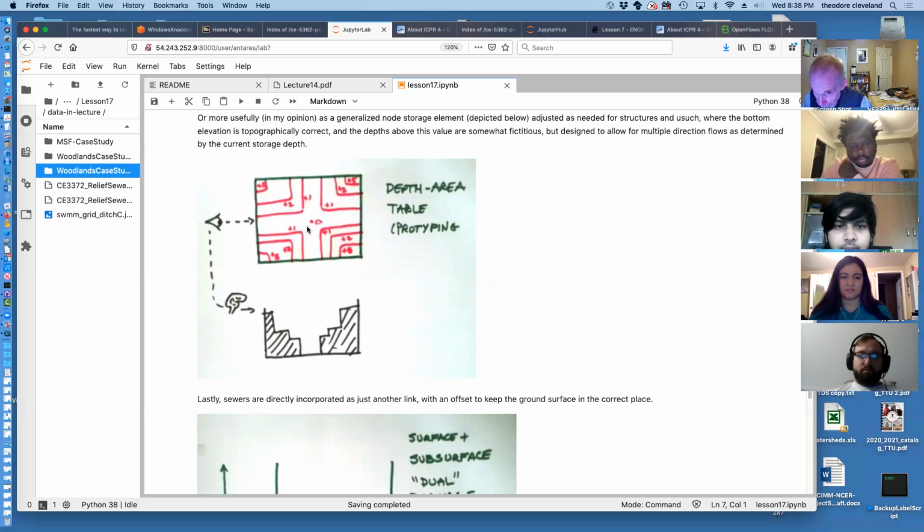But we're looking down on this node. At the center of the node, we declare the most bottomness of the node, and then it ramps up from the center to the corners. That builds these little steps as I've drawn it. For example, if the water depth in the node is 0, there's no storage and no area associated with it.